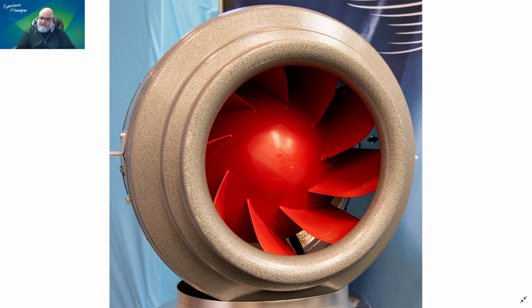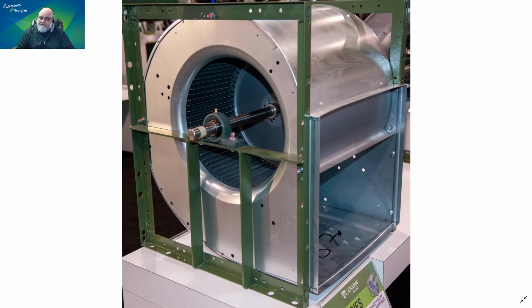This is obviously a propeller fan, and you can tell that the direction of the flow is this way. What these blades are doing is they are pushing the air as they turn. They push the air against the walls, outside walls, where the air now has nowhere to go but the other way. So this becomes the suction side, and the back becomes the supply side. This is typical, I would say, forward curved.